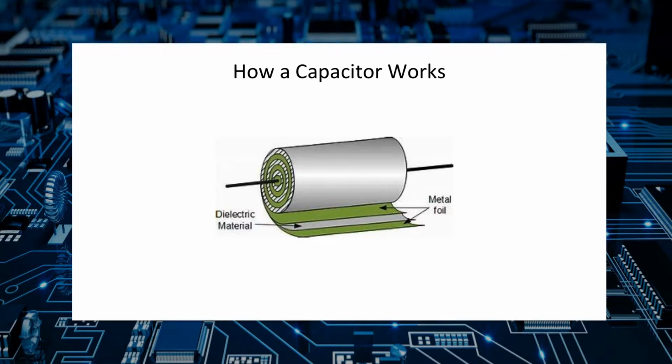In fact, it's considered a best practice to derate the capacitor, and that is assume that the stated voltage is just a suggestion. Usually you want at least a 50% safety margin over the stated voltage on the capacitor, just to be safe, especially with electrolytic capacitors.